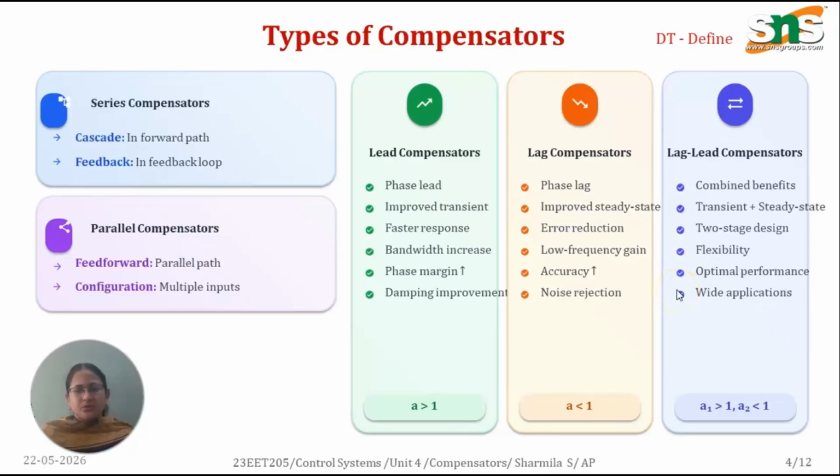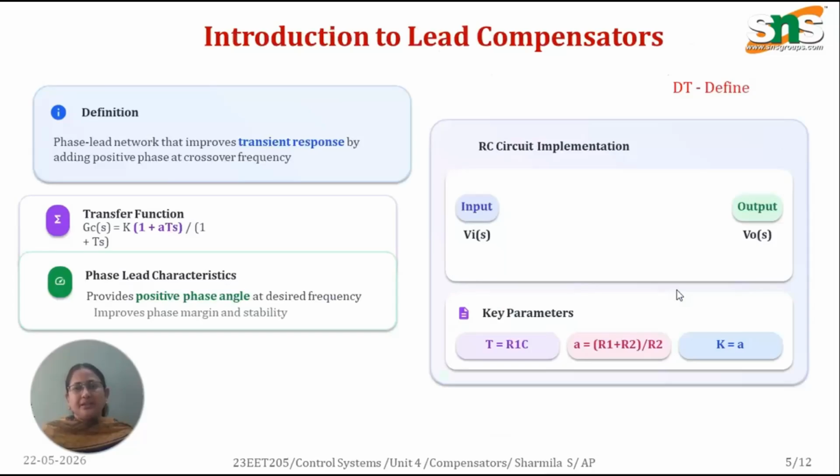So let's move on to the introduction to lead compensators. Now let us focus on the lead compensator. A lead compensator is a phase lead network that adds positive phase angle near the crossover frequency. The main purpose is to improve phase margin, increase stability and speed up system response.